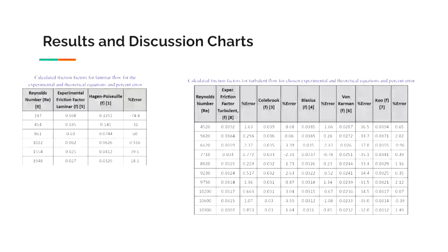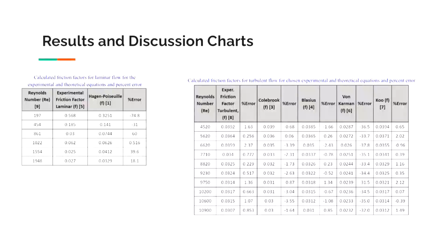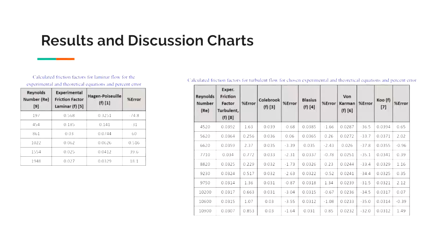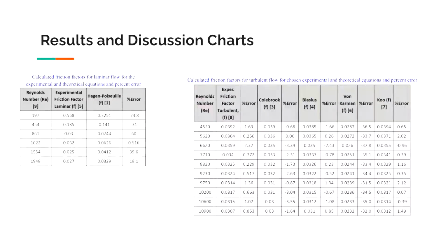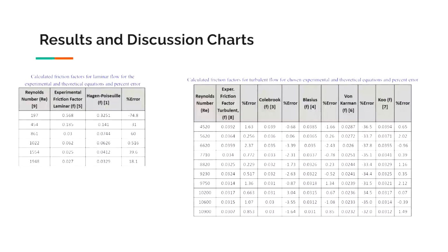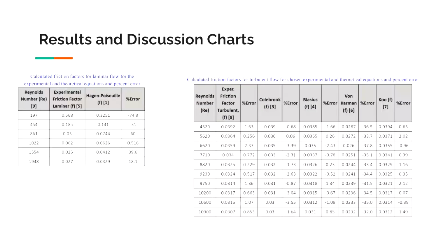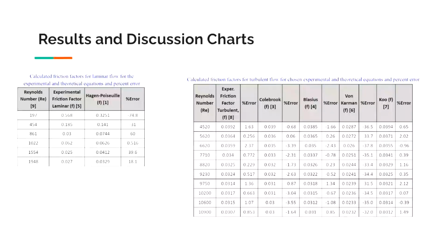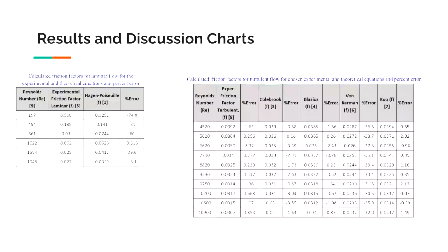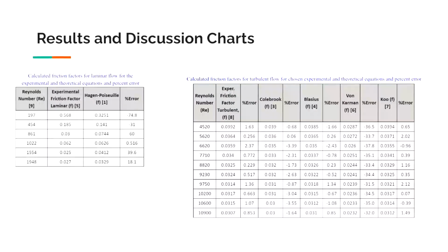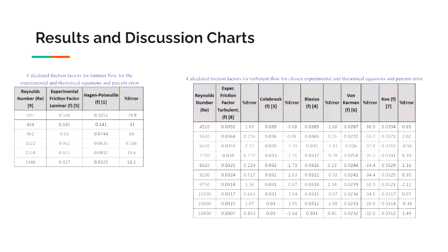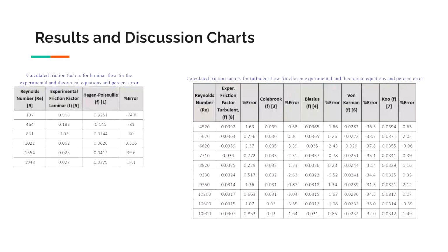The experimental results compared very well to a few of the turbulent flow expected values with the exception of the von Karman equation. And the results for the 4 approximation methods showed low % error, proving that they are good approximations for a friction factor with turbulent flow. The friction factor for laminar flow using the Hagen-Poiseuille equation yielded much higher error than expected. With this being a well accepted equation, the error comes from the experimental friction factor rather than the approximation. The slight downward trend in error suggests that the trials with the lowest flows are most reliable, with the smaller error correlated with the higher Reynolds number.